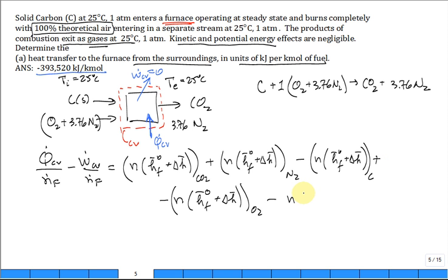Minus stoichiometric coefficient, enthalpy of formation, nitrogen. All right, I pause. Do you like that equation? Let's point out some things. It looks like this is nitrogen and that's nitrogen. One place I'm adding nitrogen and one place I'm subtracting nitrogen. It can be very confusing. But this is the nitrogen that's going out with the products. This is the one coming in with the reactants. True? So in some cases, it could go out hot, where it may have come in cold.